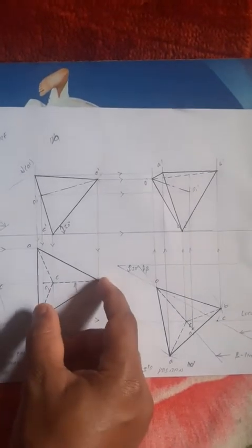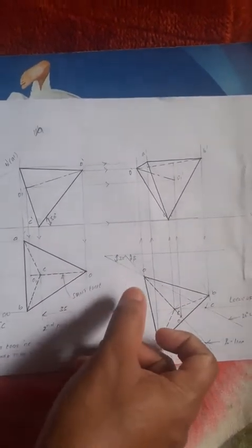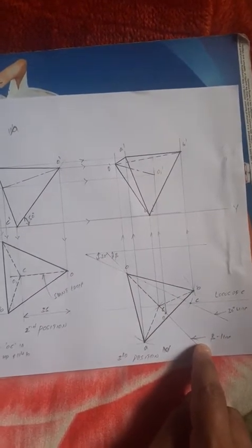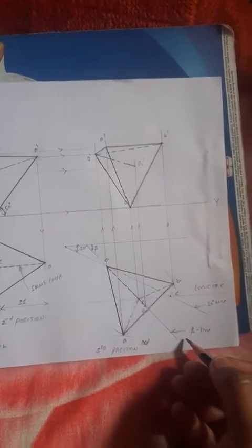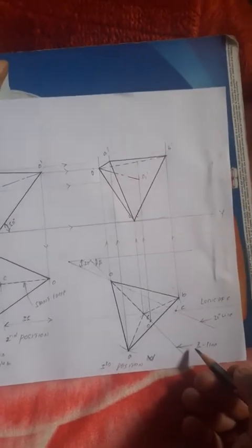From this point you will get a locus of C. Draw a horizontal line, that will be the locus of C. Then take the second position top view. OC, how much is it? 35 mm. From O, draw an arc that touches the locus of C, and you will get the second position, right? Top view, that's OC, that is the line. If we extend this line C to O, you get the beta line, right? Now how much is the beta angle? You will not measure it here, I will tell you this angle.